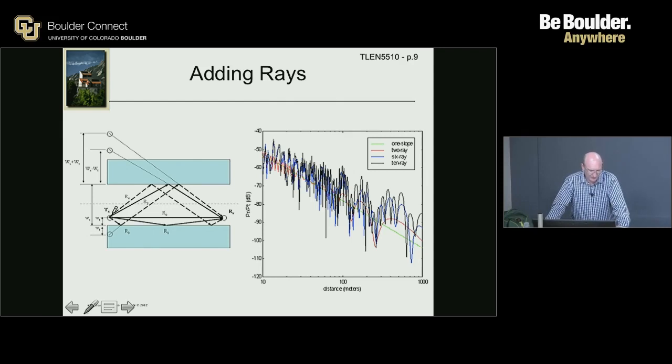If you consider one building, you should probably also consider the other one. So there's R2 that bounces off another building. So think of that as an urban corridor. You go down the street, and if you consider R0, R1, and R2, how many rays do you have? 6. And that's the blue line here. I'm not sure if you can still see the red line. It was the one we saw on the previous slide, right? It's got deep fade until the critical distance, then it's 1/d^4.